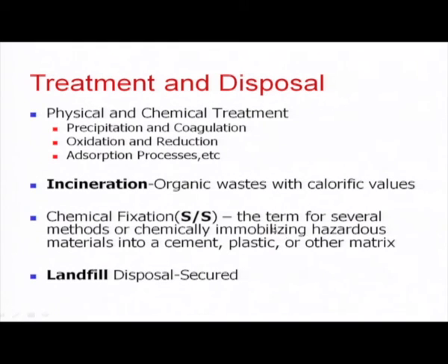And here chemical fixation is a term for several methods of chemically immobilizing hazardous material into cement, plastic or other matrix. Cement is mainly used for inorganic things and plastic especially for organic toxic material. So, depending on the nature of the base material we can select, and ultimately if it is stabilized and ensured it meets the TCLP norms, it can be disposed in a landfill. That is, a scientifically secured landfill is used for this.